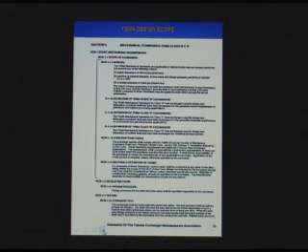Basically, the first half up here talks about the inside diameters up to 100 inches. It talks about design pressures up to 3,000 psi. It will define that typically on all of our petrochemical process work, we will use TEMA-R. There are two other types. There's TEMA-B and there's a TEMA-C.